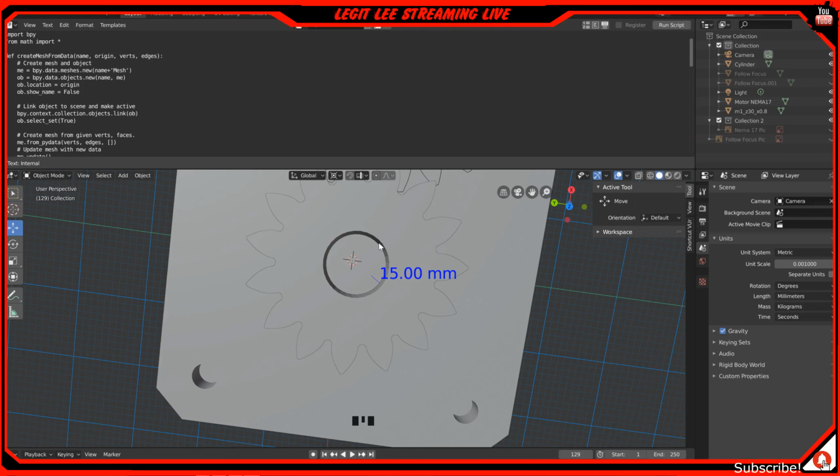Like I mentioned, there's going to be a little bit of a gap. That's just for shrinkage because it's going to probably shrink down. I mean, yes, you can do 5 millimeters. Then if it's a little smaller than that, or if it shrunk down, you can theoretically put a drill bit on it or something, or even try to tap it in with a hammer, but you don't want to damage your stuff. So just add a little bit extra. It's not going to kill it. If it's throwing it off, then you can go back, redo it, and change the size down a little bit, make sure it's a little smaller so it has enough grip.